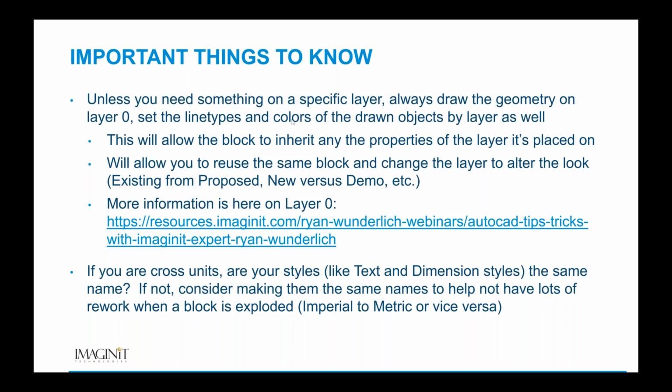You can put it on a new versus a demo layer. All of those things will be inherited when you simply change the layer the block is on, if it's all drawn on layer 0, line type by layer, color by layer.